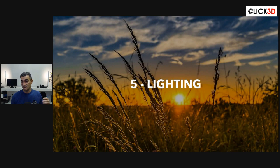So if you're in a completely pitch black scene or room or whatever, you can still capture data. You'll still have geometry. Now, there is a camera in there as well that's going to be capturing photographs, and that is what will suffer. So if you're trying to capture beautiful colors in a very, very dark environment, it's just not going to happen. Now, many laser scanners today have high dynamic range and that sort of thing. They're okay. They're not too bad, but they're not fantastic. They're not going to give you the same result as a really nice digital SLR camera.